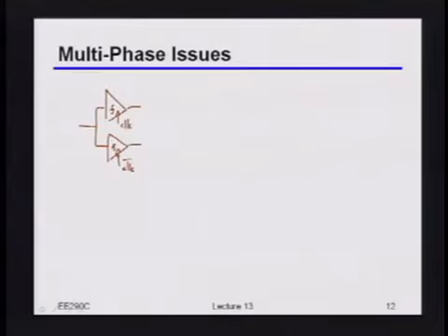But maybe that's not so bad, because you could take your phase interpolator and do some sort of phase splitting and get both clock and clock bar with the same phase relative to the reference clock. So that seems reasonable. Let's call this the full rate design.